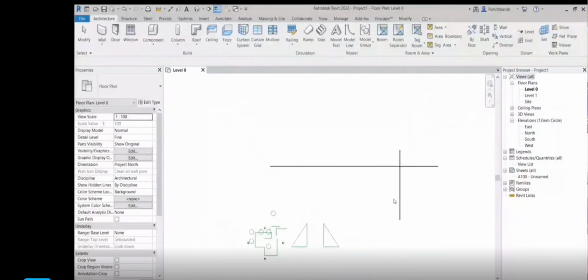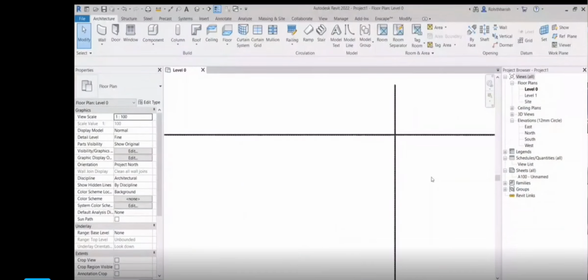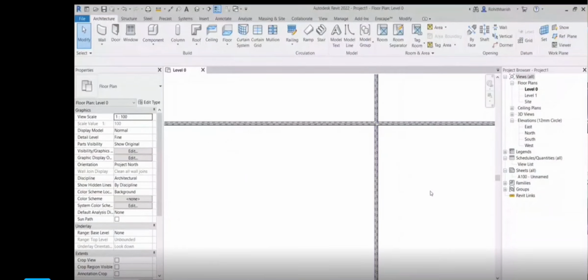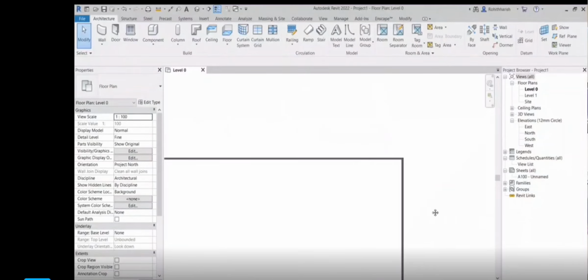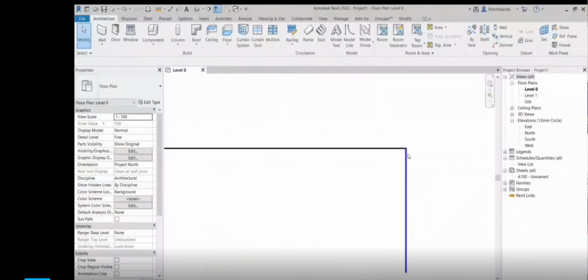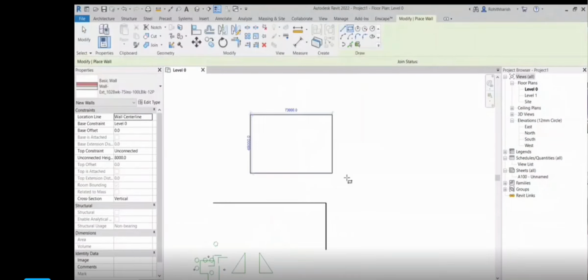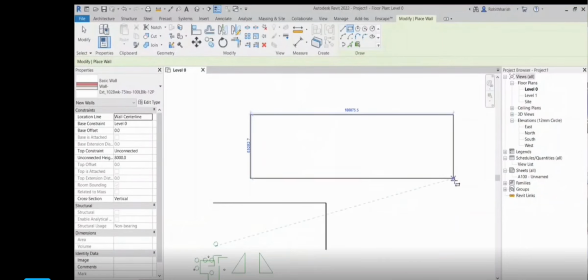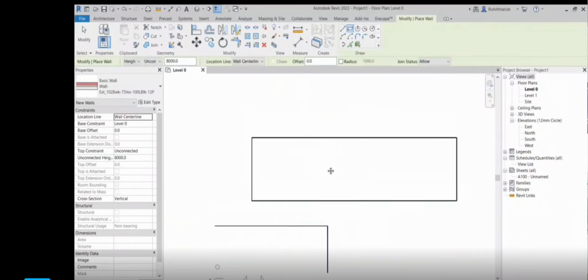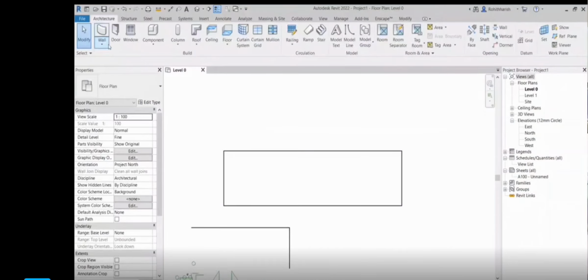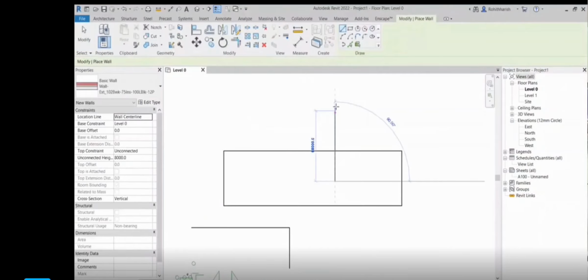Just like what Sunena said, I'll go and create a wall like this. Say my shape is changing somewhere here. Just a second, like this. Now if I go and trim this particular side, TR, this and this, it will trim the complete wall here. Am I right?